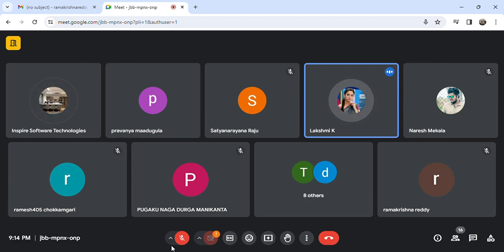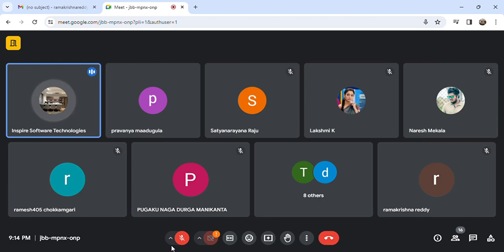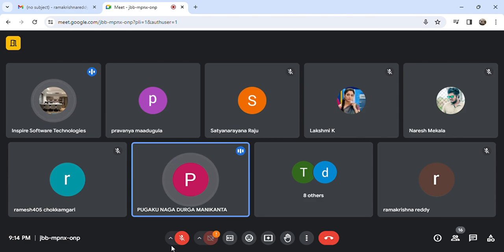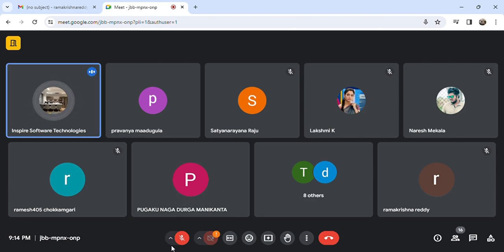Acknowledgement delimiter bit. Recessive bit. No, in the acknowledgement slot, not the acknowledgement delimiter. I am asking in the acknowledgement slot, the transmitter has to send one bit, and one of the receivers will toggle that bit. So how many people are saying it is a dominant bit?